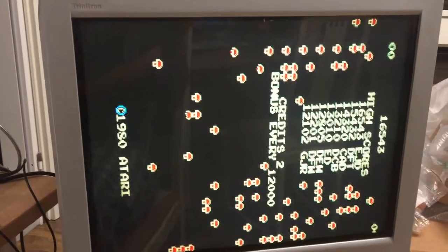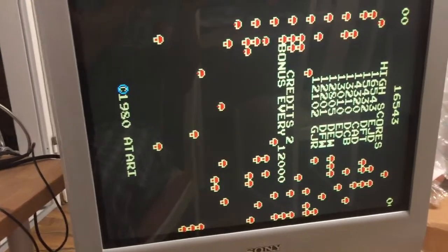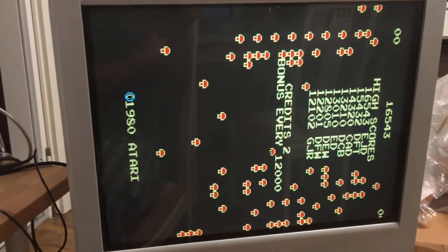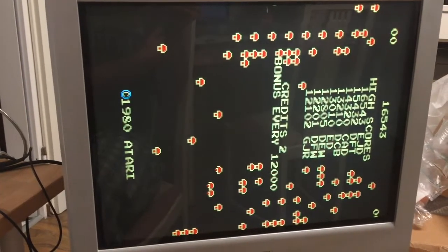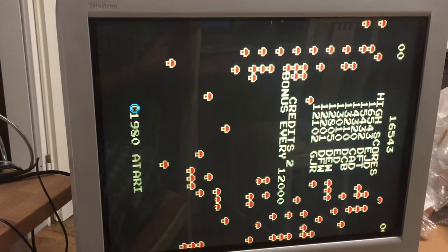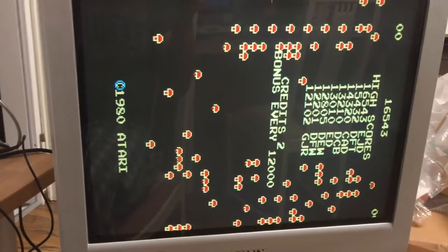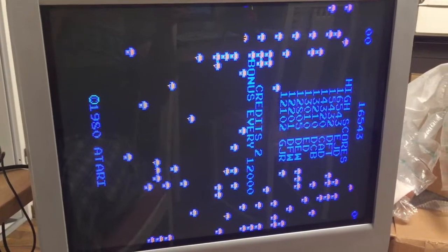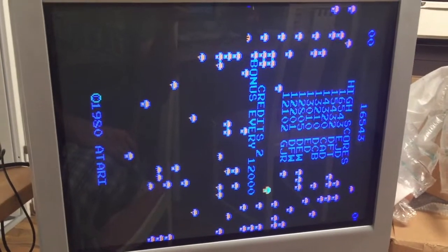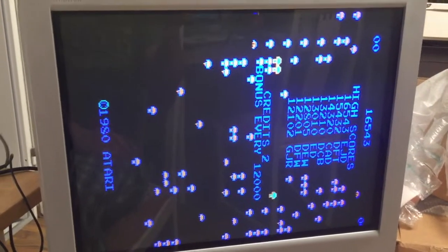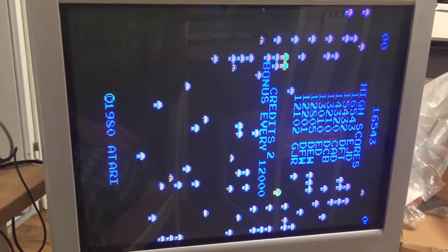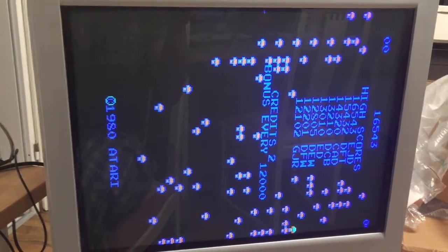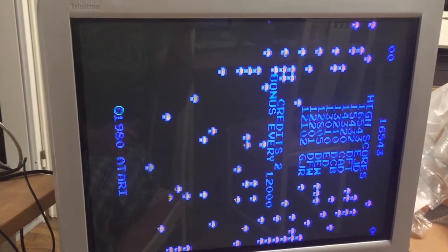But the rule that I'm talking about is that if you have a complete loss of a certain function or aspect of the game PCB, as opposed to something glitching up, then that most probably means that the problem lies either at the very end of the circuitry that is related to that function, or at the very beginning of it.